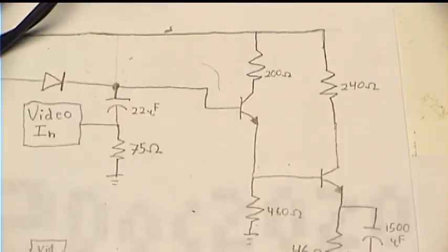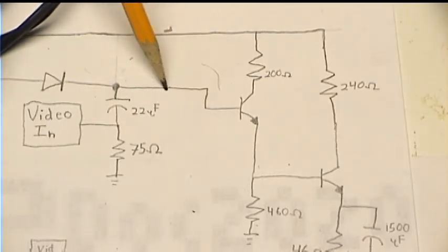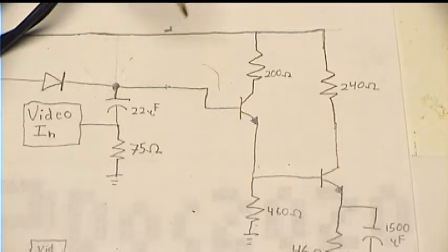And as I mentioned earlier, video signals are AC coupled, so the actual voltage itself doesn't matter, it's only the changes in voltage. And that's why it's okay to run the video through a capacitor. It shifts the voltage up, so the low pulses in the video, once it gets here, are at about 3.7 volts. And then the higher parts of the signal are still that much higher, as they should be.